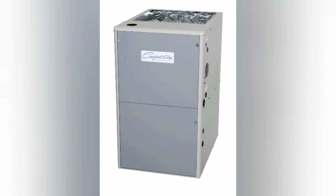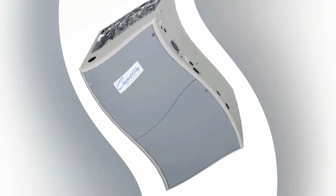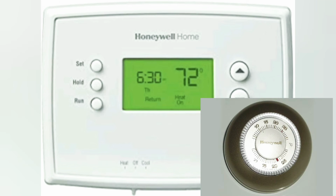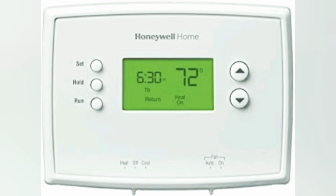Now we're going to get into basic reasons why that might not work, and what may be causing issues with your unit. This brings us back to our thermostat. If you have a digital style thermostat, you need to check the batteries to make sure they're in good condition and putting out the correct voltage. Improper voltage can mean a faulty signal is being sent to the heating unit, causing it to shut down prematurely. If you have a dial style thermostat, you may want to consider upgrading to a digital style. They've just outlived their lifetime and usually contain harmful substances like mercury used in the switch mechanism.